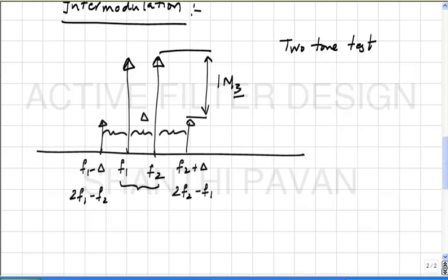So, can you comment on the intermodulation distortion at very low frequencies? Why? So, again there is nothing to think about. At very low frequencies, as we just saw, the output will be the same as the input because it is f of f inverse or f inverse of f of x type thing. So, Vout will be equal to Vi, which basically means that it is a linear system as far as low frequencies are concerned. So, there will be no intermodulation distortion, it will be very low, right.